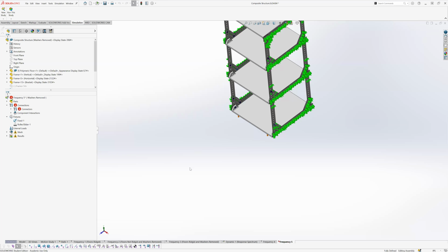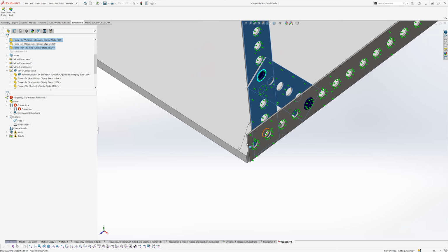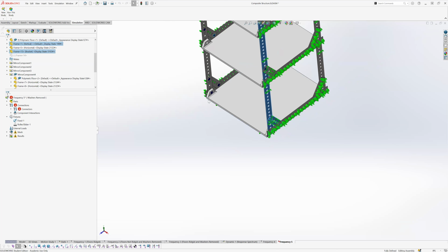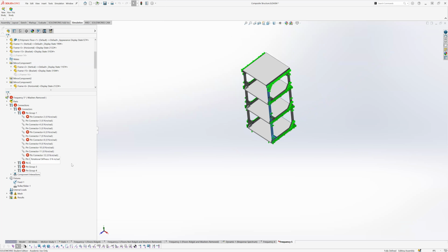Since the geometry has changed, obviously the washers are not there. And if you recall, for our pin connections, one of the faces we actually selected was that inside face of the washer. So we're going to have to go through and make sure we account for that. So we go into our connections, under our pins. You'll see a few different pin connections that are affected by that.